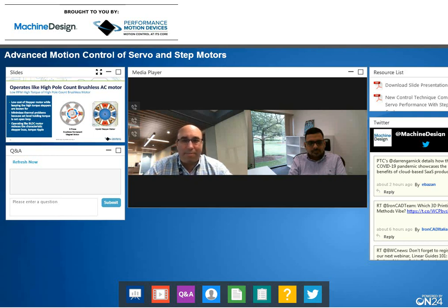And that's where stepper motors have been amazing in this area because they were invented, and commonly used, I'll say, well before brushless permanent magnet motors and the control techniques for that, because there's simple mechanisms for them to be controlled. And that picture on the far right-hand side where it says hybrid stepper motor kind of shows this layout where there's all these little blue and darker colored points around the radius, and you're looking at just the south pole of that. There's a north pole buried on the other side. And it gives you a whole lot of those pole pairs that we're talking about.